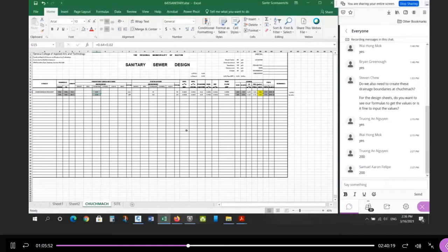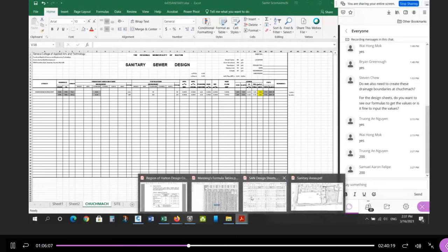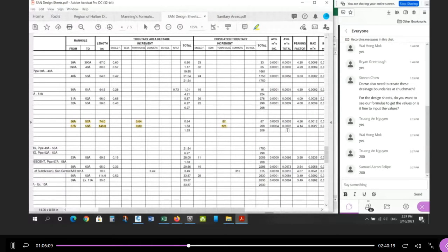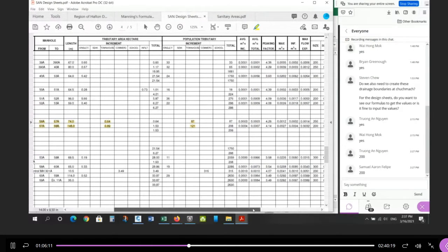And two, it gives you an opportunity to program the spreadsheet so that now you can copy and paste formulas into the actual proposed subdivision to design your pipes. And the nice thing is if you do this one first, because you're calculating things that you have solutions for from the PDF, you can check your formula programming, right?